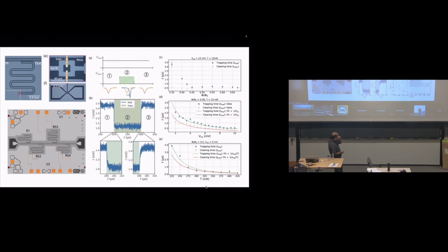So something that I just want to flash, because it's part of this sensing and the resonator, is that if you have a resonator, basically you have a frequency, right? And this frequency could change based on how the resonator elements are changing, right? But what you can make this resonator into a quantum sensor is by adding basically a SQUID loop at the bottom of this resonator. So now instead of having a resonator that goes through a gate to ground, I can make a resonator that becomes a SQUID, but it has 2 gates.